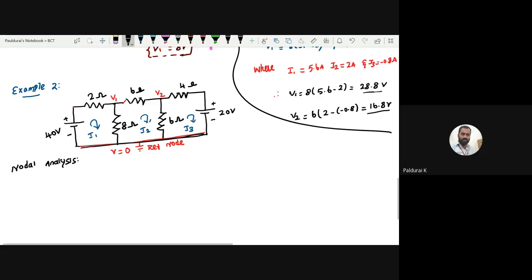Okay, so now what is the very first step? Now coming to node 1, to apply KCL at node 1, what do you want to do? You want to assume the current direction. The best practice: always assume all are leaving currents. So 3 currents, there is no entering current. So 0 equals. Okay. What is the very first current? Take this as number 1, this as number 2, and this as number 3. So this time I don't want to draw separate branches, and you know those 8 cases.